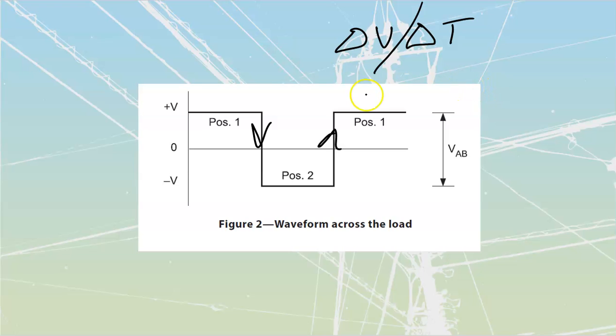This waveform will need to be cleaned up. What we're going to do is slow it. You should remember that we've got a couple of components that will slow the rate of rise of something. I can slow the rate of rise on the incoming like that. I can also use another component to slow the rate of drop. So I can have a slow rate of drop, slow rate of rise. It kind of switches, and we will be able to utilize those filter sections to clean this thing up.